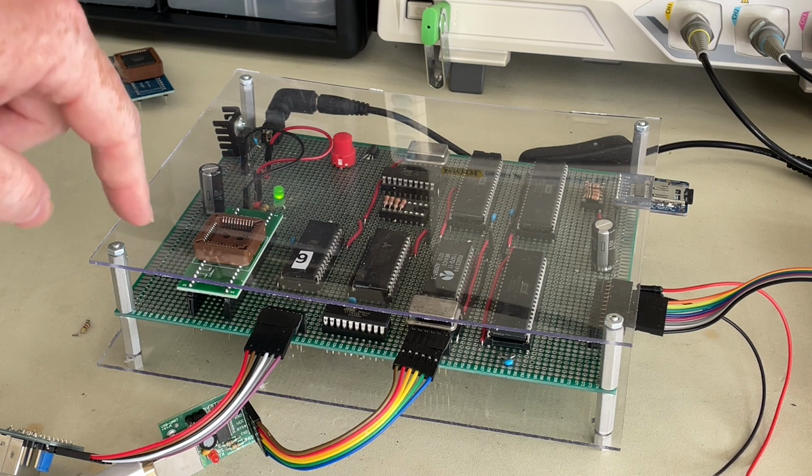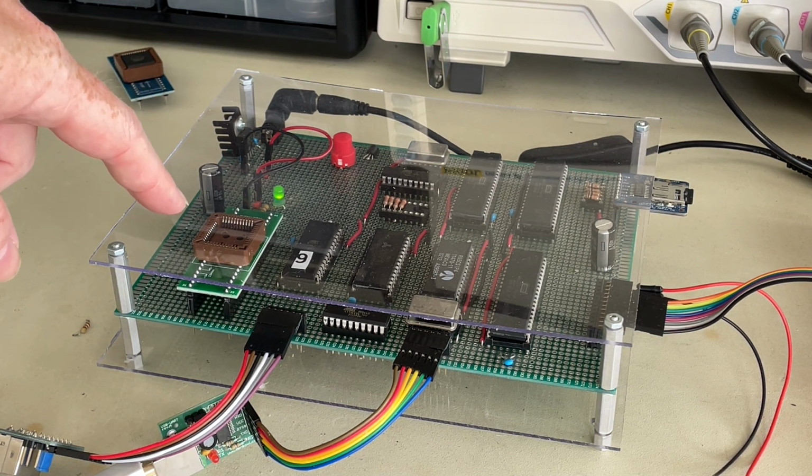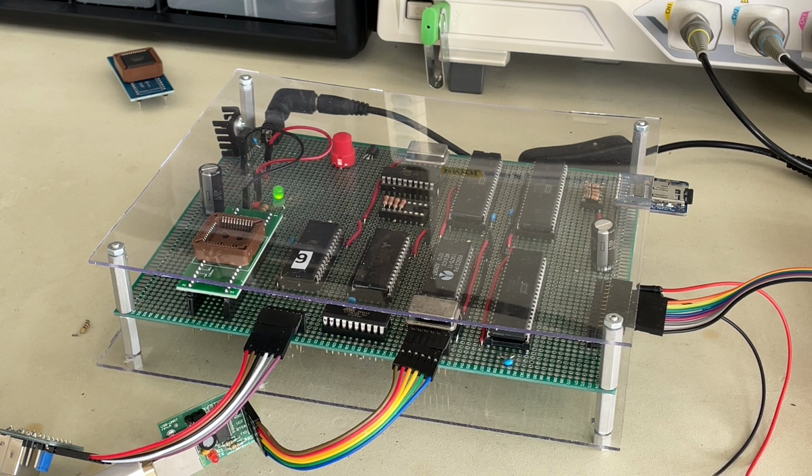You can see here perhaps that I've already got a spot on the board where I'm going to put the 65SPI. This is a sort of weird combination of a PLCC 44 to DIP adapter and then some headers so that I can wire wrap it. But before I'm able to put that in, I'm going to have to program the thing because the 65SPI uses an ATF1604 CPLD. So I'm going to have to program the CPLD, and in fact, to do that, I've got to build a programming cradle, which is probably what I'm going to talk about in the next video or two as I try to get that working.